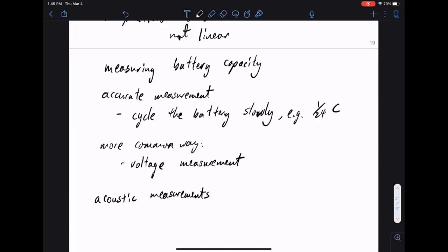The hardest thing about using secondhand batteries is actually figuring out how much capacity they have. You often don't know. You got a battery, and you often have no idea what is left in it. And if we're going to cycle every battery from a bus we get through 2 days of spare capacity, we don't have that many cyclers sitting around. Right? So this is an important issue for us to use batteries.